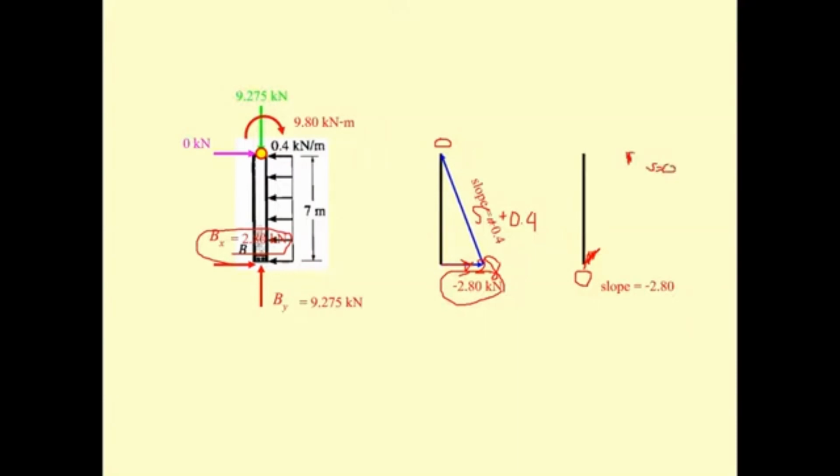And the moment here is supposed to be 9.8, and it's going to be minus because it's on the right, on this side. Okay, from over here 0, and then slope is negative, so this one is going to be minus 9.8 kilonewton meter, and the curve going to be like this one. Okay, and then we have 9.8 what? Clockwise, and then it's going to be positive. Okay, it's going to be like this, and close the loop here.